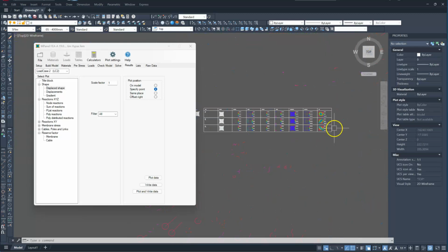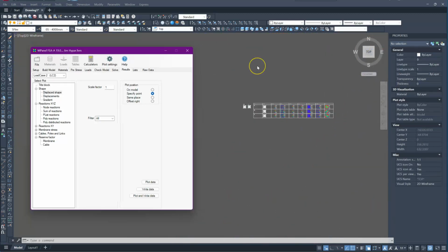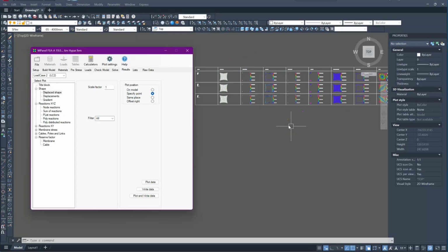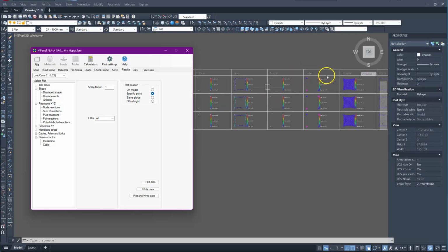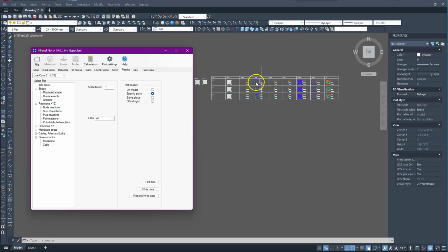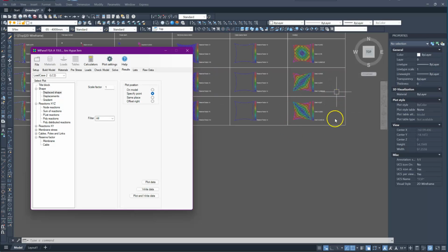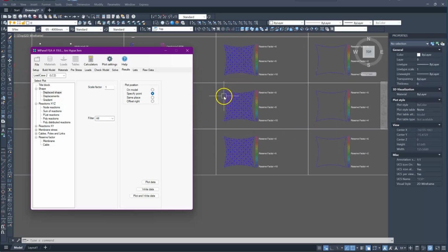So there you have it, a simple method to import a model you've created in Shade Designer into the FEA for analysis, to determine the size of the poles, to estimate the size of the footings, and to check for water ponding, and also check that the capacity of the fabric is adequate to the design.